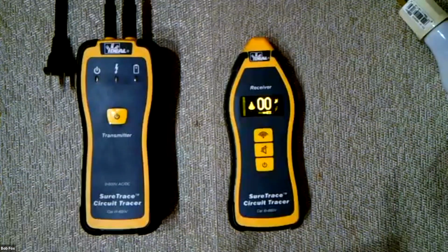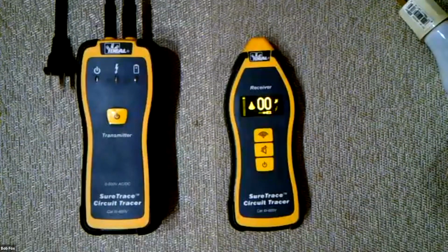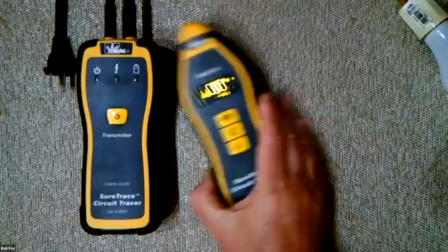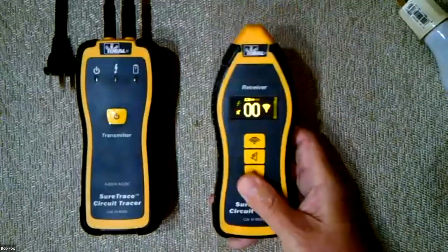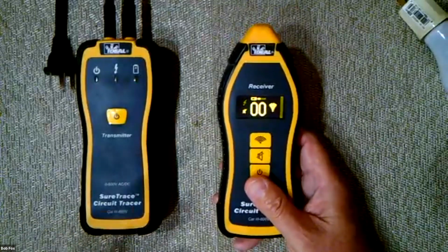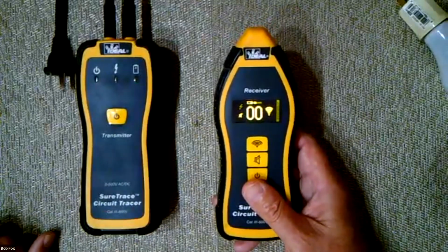On that very note, just very briefly, when I'm outdoors doing underground tracing, I hold it at waist level. You don't want to go back and forth, tilting it up and down, but I hold it at waist level, comfortable, and I look at it. In most cases, I can do just fine tracing.